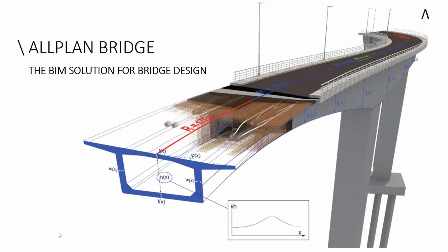When you then assign this table to the cross-section, the program can automatically read the respective value of the dimension for each station. In this way, the user just needs to define one single cross-section, and the program will automatically calculate all the deriving cross-section variants along the axis.